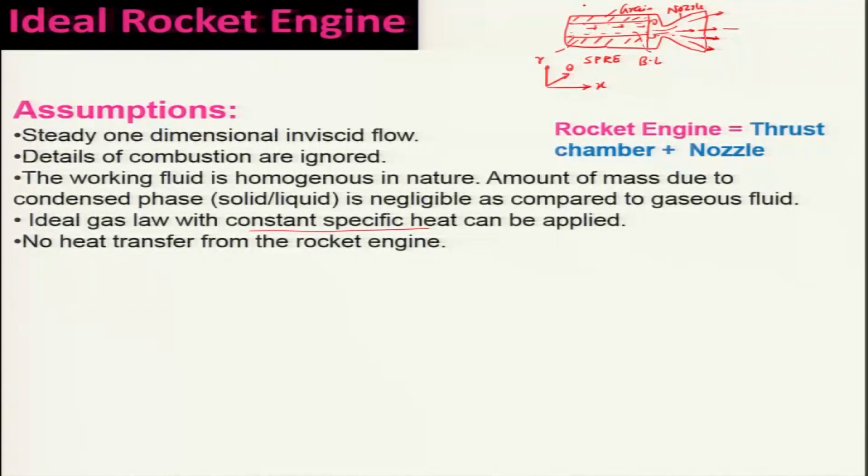But actually there will be some heat transfer, at least in solid propellant a lot of heat losses will be there from the nozzle and also in other parts. So that is not true, and we are assuming it to be zero, or adiabatic, but that is not true in real situations.